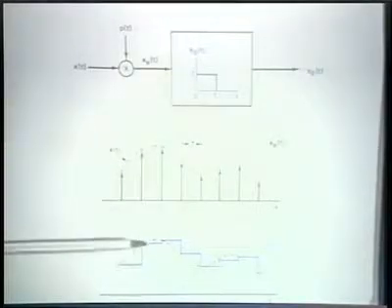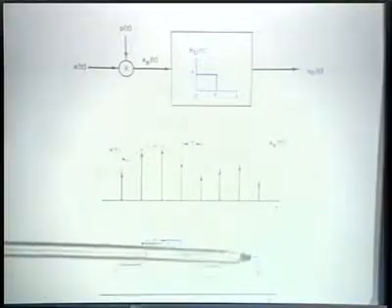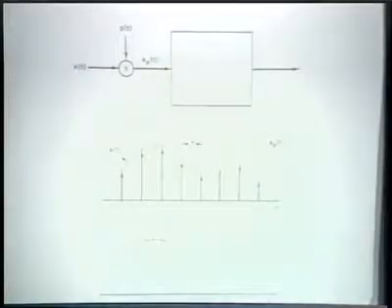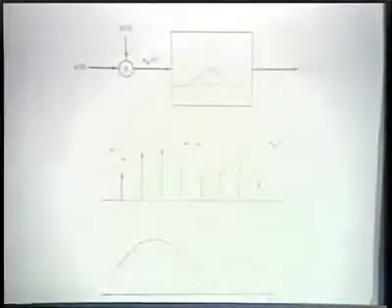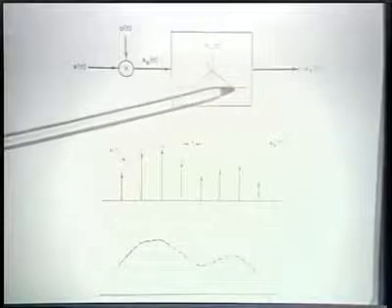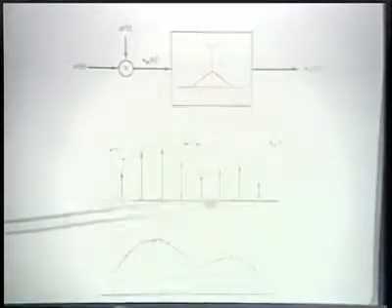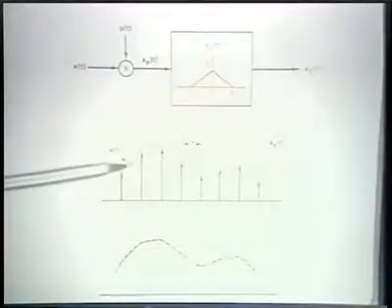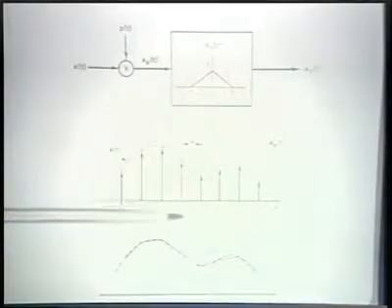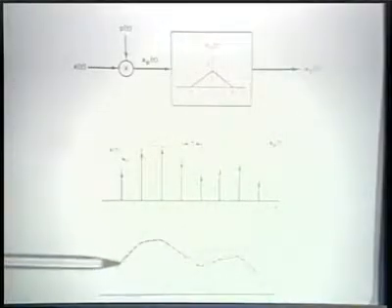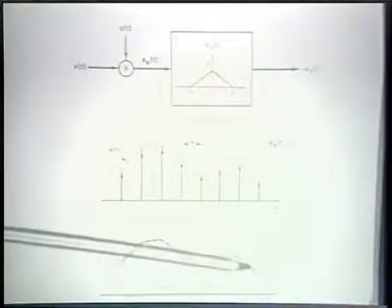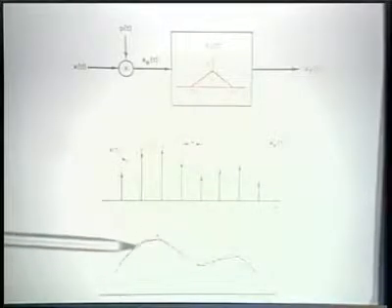That will generate then our approximation, which is a zero-order hold. And following that, we'll do exactly the same thing with the same waveform using a first-order hold or a triangular impulse response, in which case we'll see again that as the triangle moves along here and we build up the running sum, or the convolution, we'll in fact fit the original curve with a linear curve.